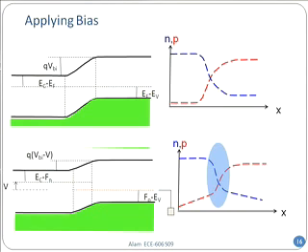Similarly, the red is large on the right, very small on the left, and falls in between. In equilibrium, if you take any two points at a given location and multiply n and p, that value is always equal to n_i squared. Therefore, there is no recombination generation, because the numerator of the recombination generation is np minus n_i squared. In equilibrium, there is no net generation or recombination.